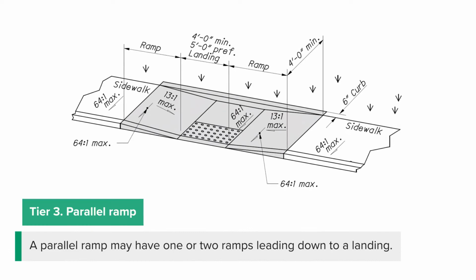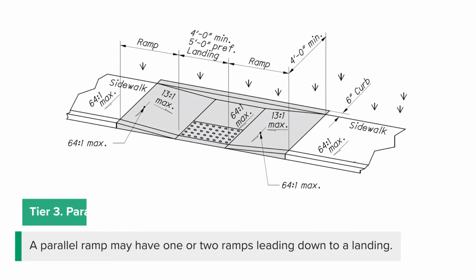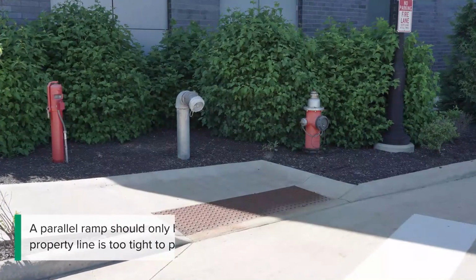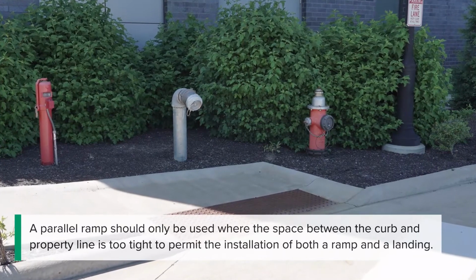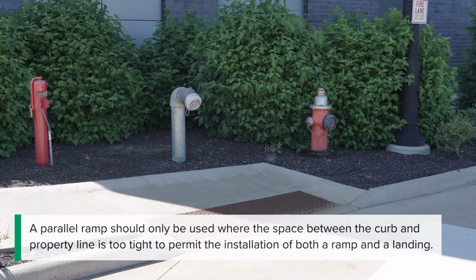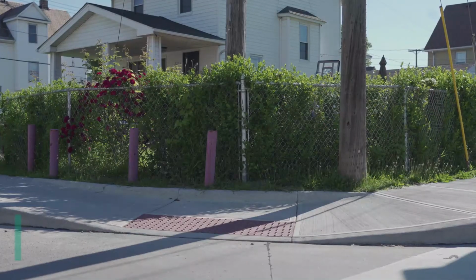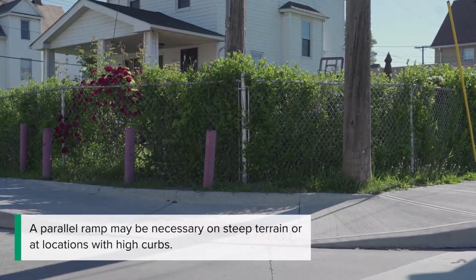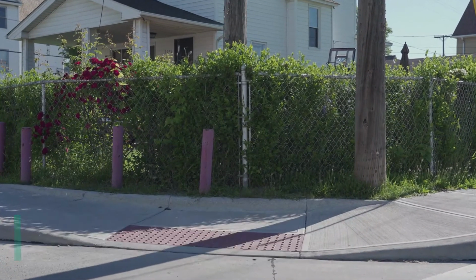A parallel ramp may have 1 or 2 ramps leading down to a landing. A parallel ramp should only be used where the space between the curb and property line is too tight to permit the installation of both a ramp and a landing. A parallel ramp may be necessary on steep terrain or at locations with high curbs.